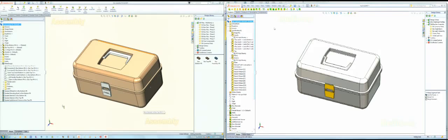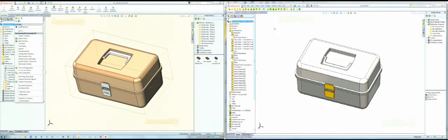But, and there's a big note in here, don't do this yet because bad things happen. You have to lock the references. And if I make the mistake in here and try to do that, you'll hear Tom Hanks saying, Houston, we have a problem about 15 times and SolidWorks won't let me do anything. So you see all these external reference signs here. We have to lock all those references. Either that or get rid of them.